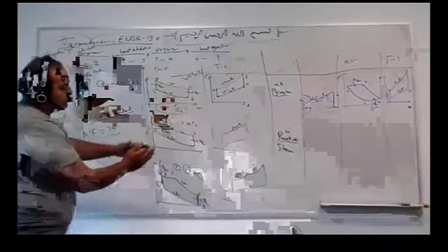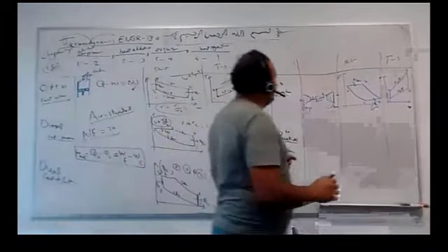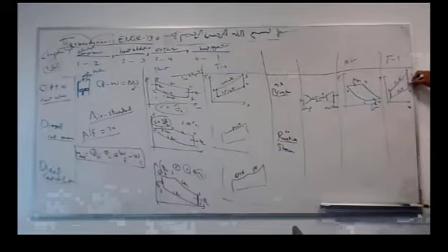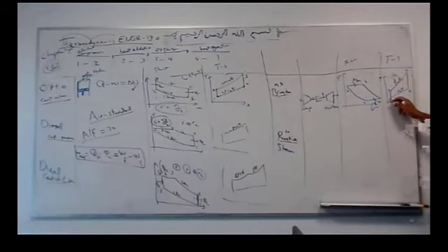The volume lines diverging, the pressure lines diverging. So in the Brayton cycle, in a jet engine, how we create thrust for an airplane, this is exactly the topic. All the pressure lines are diverging at the top and converging at the bottom. That's why we pay less in the compressor and get more in the turbine by paying some heat. That's why if you compress and expand, you get nothing. You go vertically and downward, and that doesn't give anything. And if it's real, not ideal, it's even worse because you're going to go slanted, so you're going to get much less than what you paid for.